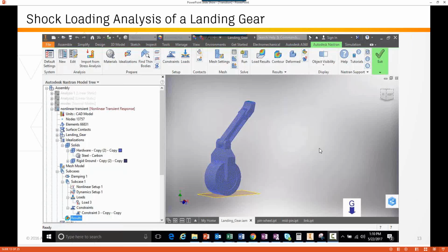Essentially, we're going to say that the landing gear is out, and all of a sudden we hit a big bump of turbulence. When we model something statically, we're saying we're applying that load very slowly. In order to apply a shock load, I need to be able to change the load versus time. You're going to see inside this quick demonstration how I can change the loads versus time, look throughout the life of the quick cyclical behavior of this analysis, and target in on those times where I might need to identify specific behavior.